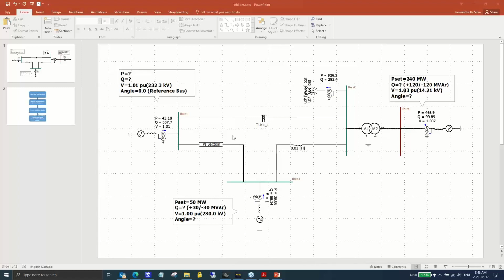And now you will again have the correct power flow. But maybe you don't want to go there, right? Or maybe you did not create this case using an existing data file. You probably just created this with data that were in data sheets, right? You just manually created the case without PRSIM. In that case, how do you ensure that you get the correct load flow?